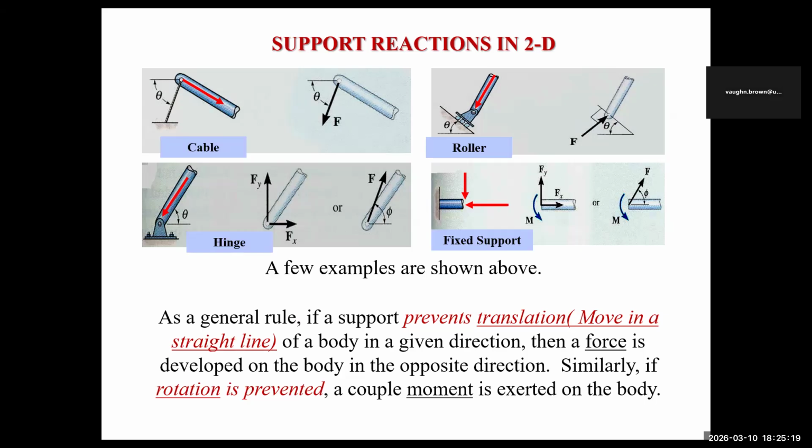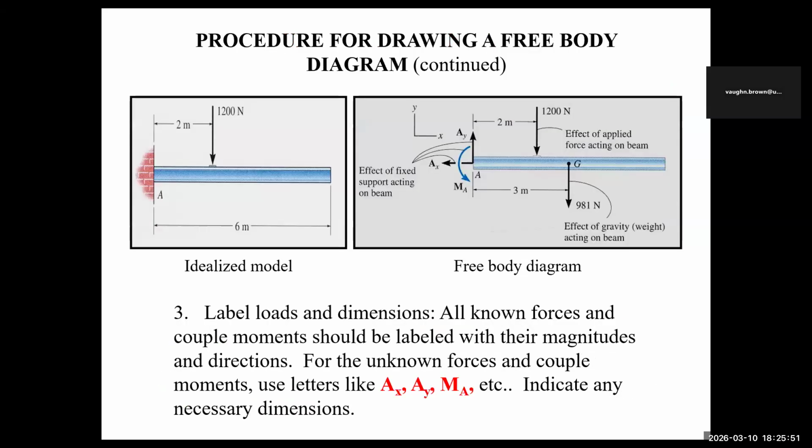Look back up top now. We have a roller that is rolling on an inclined plane. Whatever direction you're rolling, you will have no reaction in the direction that you're rolling. So if you're rolling along the inclined plane, no reaction, but you will have a reaction perpendicular to the plane, which you can see is at a right angle to it up here in the roller. I hope you are seeing my pointer. And then the last one, cantilever again. This is how we know to draw the cantilever on this frame around here, right?